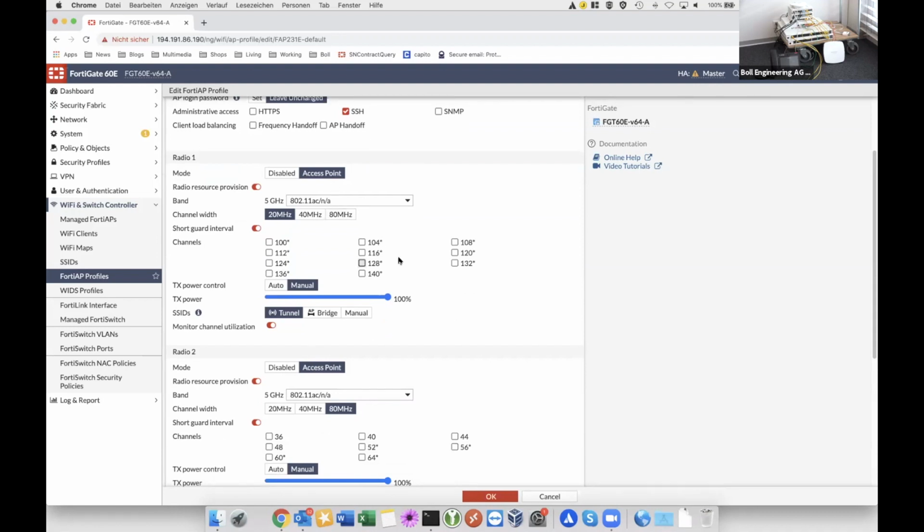And the lower radio, radio 2, is only available to send on 36 to 64. This is mainly because those channels need to have space in between each other. You can use two radios narrow in one enclosure, sending on the same or nearby channels. So you need to have the upper band and the lower band both in place to host dual 5G clients. This is more like a basic feature to know, but it's quite a handy radio here if you want to have high density setups.